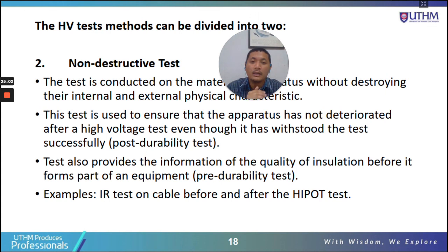Okay, basically what it says that, this is an example. As an example, in the industry, we perform high-pot tests on cable. So high-pot test is destructive test, right?